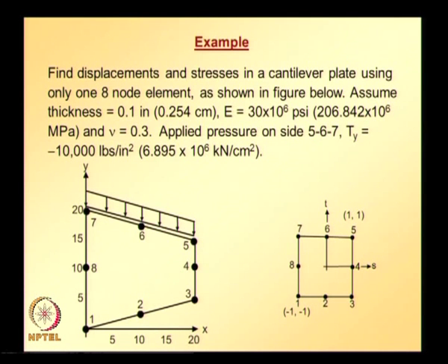So, in total, you can guess, 9 integration points are there, and I guess you know how to obtain the corresponding weights and coordinates for all these points. So, now the calculations will be illustrated for one integration point. Similar process can be repeated for the other integration points, and contribution from all integration points can be added up to get the final